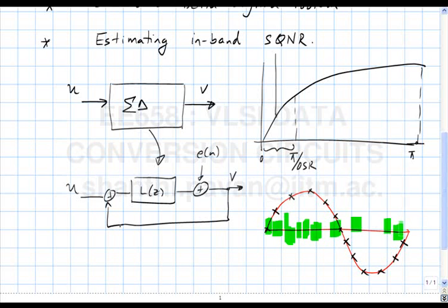So hopefully this is more uncorrelated than the earlier one, okay? You understand? If this e[n] is random noise, uncorrelated from sample to sample, what can you say about the noise sequence coming out of the modulator? It is this random sequence which is shaped by the loop, by a transfer function equal to the NTF, which is 1/(1+L(z)). But is that output periodic or not periodic? It is not periodic, okay.